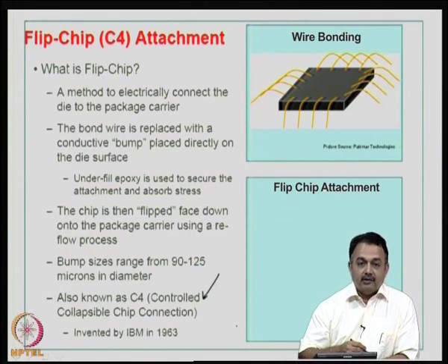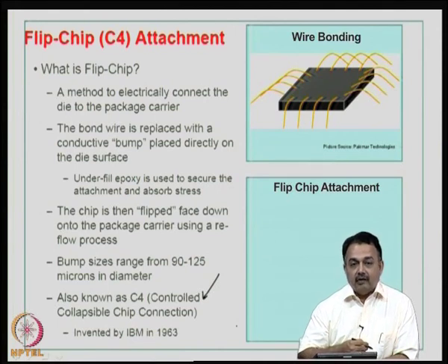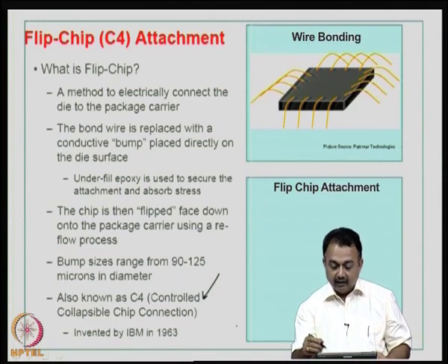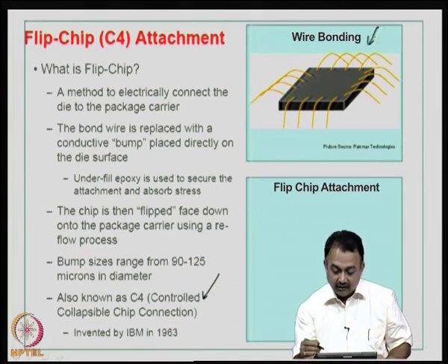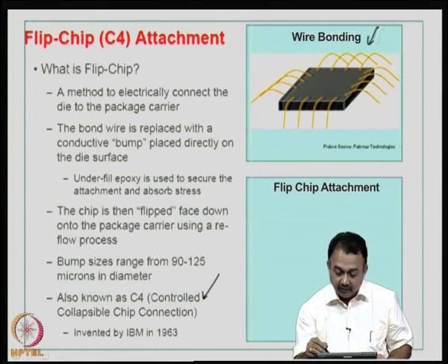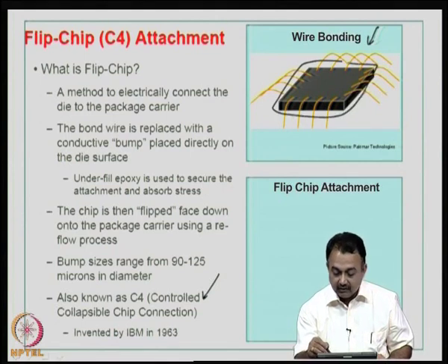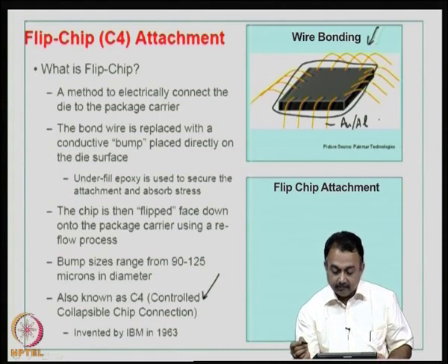Of course, wire bond has been used for a very long time in all your DIP packages and QFP packages where the profile is very high, but today with low profile components you are not able to use wire bond because it occupies more space, more volume. So, compared to wire bonding, as you can see in this figure here, I think now you are very familiar with the peripheral bonding of wire bonding. As you can see, the bonding of wire bonding process is at the periphery and here these are the gold or aluminum wires which is attached to the substrate.